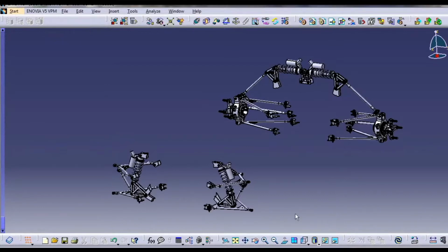While designing the suspension system, we have to consider three forces. Those are bump force, cornering force and braking force on the tire. According to these forces, the arms of the suspension are designed. While designing them, we have to keep in mind the factors of bending, shear and buckling.